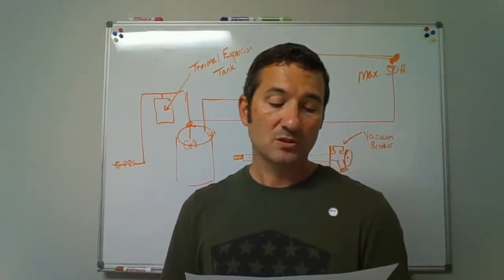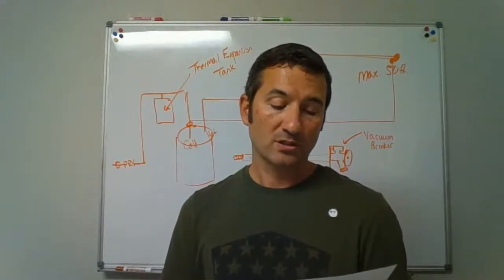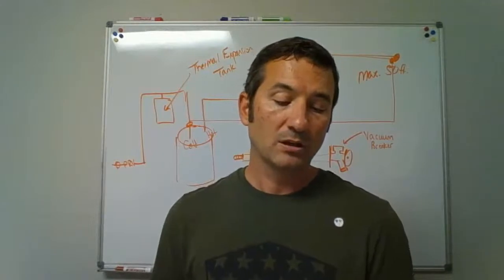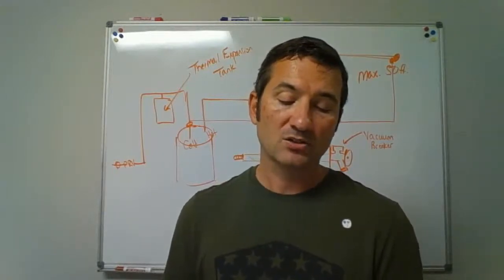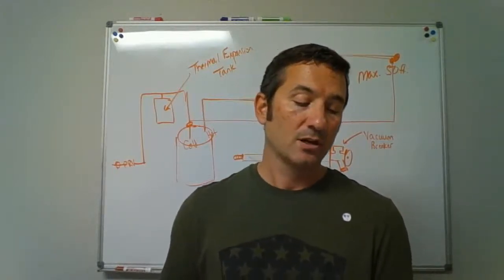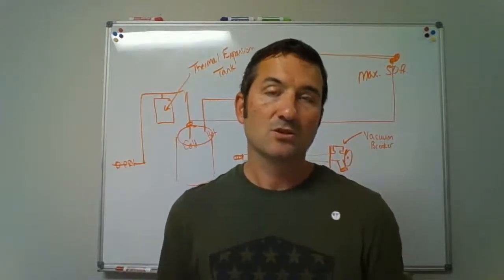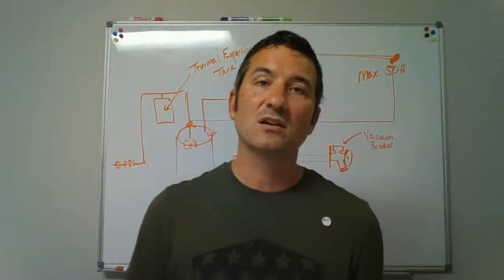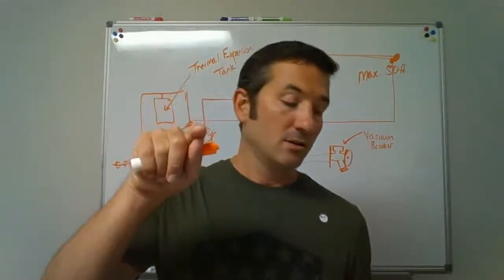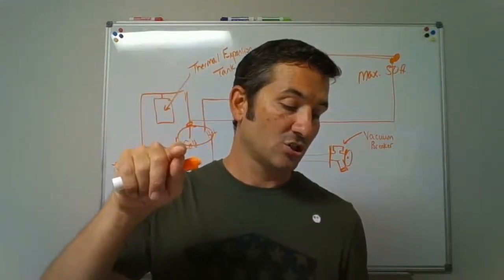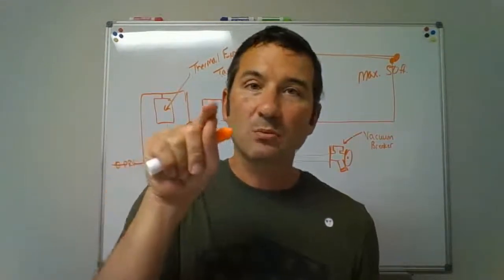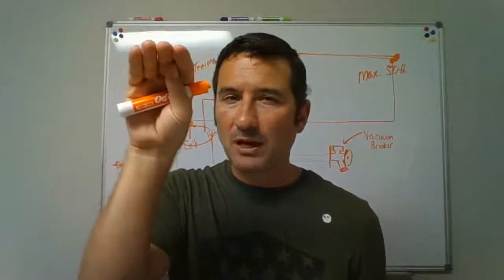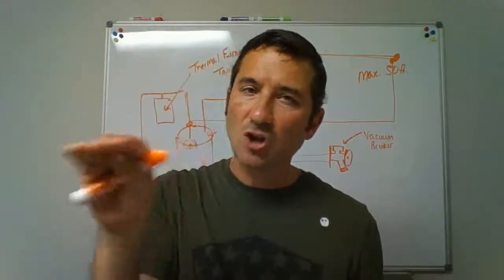The 5 steps to a solder joint are cut, ream, clean, flux, and then solder. So if you were looking for this, go back into that section. Remember what I was covering: steps to a solder joint. So probably under copper piping. How can you join copper piping? Look at it, and one of them is going to say soldering.